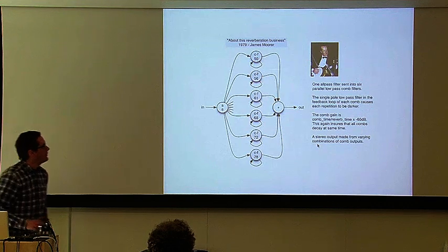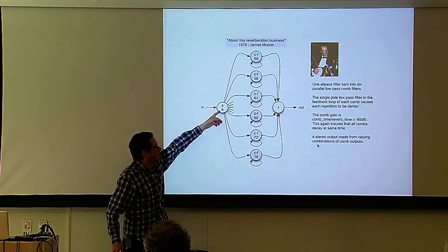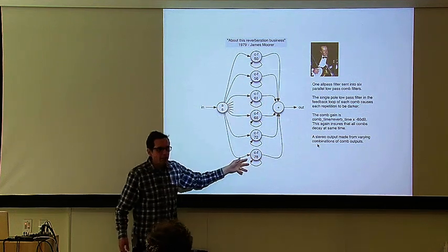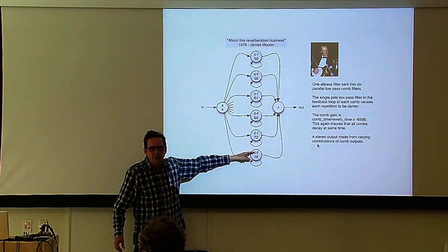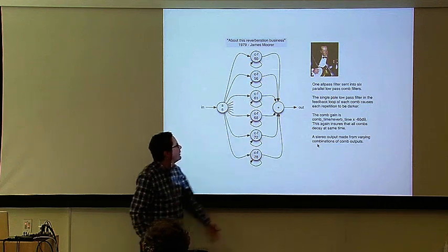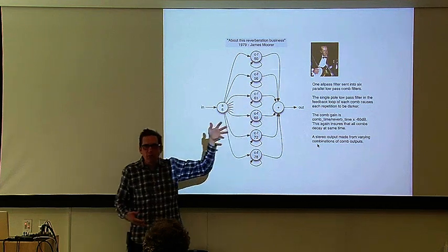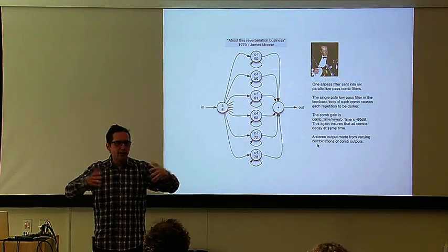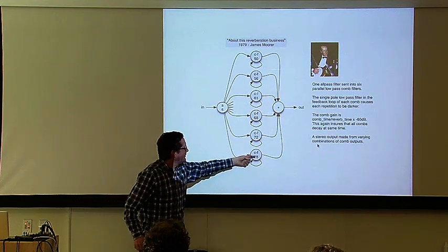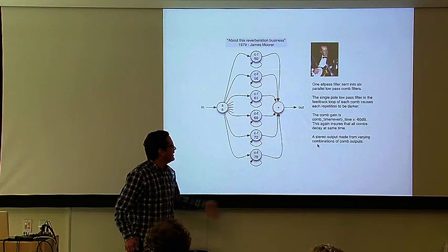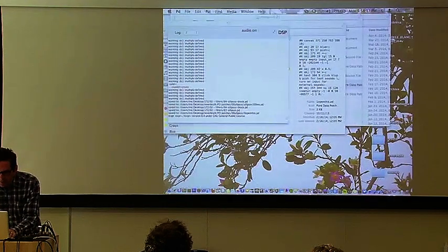We take James Moore's reverb, which is actually fairly similar. He has a single all-pass filter, and this runs into a number of parallel comb filters, but his innovation is adding a low-pass filter in each comb filter. So now this network approximates more what a hall does, where you don't get everything back that you send to the wall. Hopefully, the filter gives you a nice sort of wooden wall. It's still somewhat simple, but I do want to play this example.